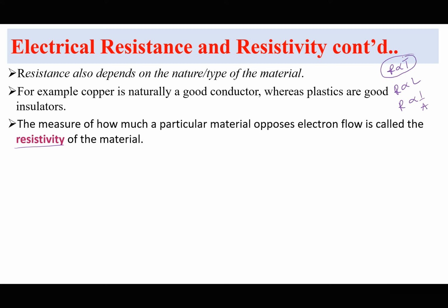Because this is a physical factor, environmental factor, we shall combine these two factors to come up with an expression which relates resistance to the nature of the material. So we shall simply see that resistance is directly proportional to L, but inversely proportional to the cross-sectional area. I will remove the proportionality sign. Resistance is going to be equal to L over A. I must introduce a constant, and this constant will be called rho. Therefore, we say resistance is equal to rho